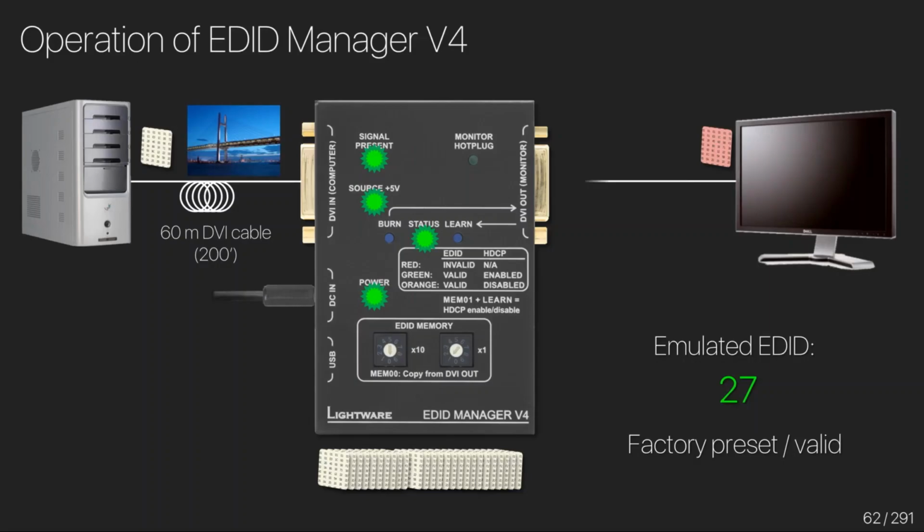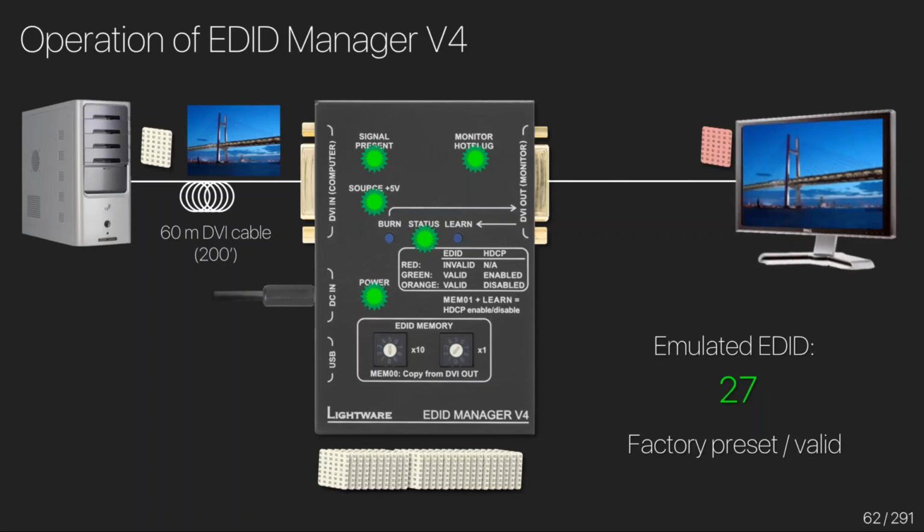And when we want to connect the display device, everything's ready to go. We get the hot plug signal, we send the video along, and then we read the EDID from the display, and we save that in a specific memory location in case we want to use it later or edit it and do stuff like that. So EDID emulation is very useful for keeping your source signals active even when there's no display being connected.